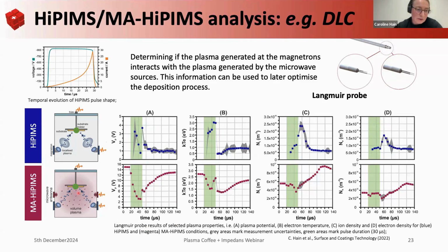So what's happening here is that when we have the magnetron plasma on, we generate a magnetron trap, so the electromagnetic fields trap the species. First they get attracted by the very high negative voltage, and they get trapped in this area. Then after the pulse, when we no longer have this field present, they are able to travel back towards the substrate. So now we have the information of when most of the ions are actually reaching the substrate. Now we can use that information.